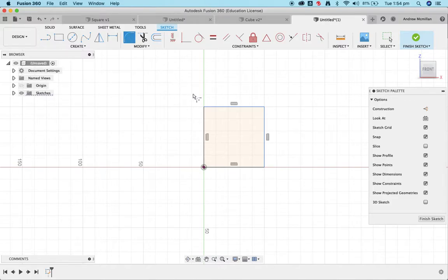Now what you'll find is if you hover over one of the corners on this, a red line comes up which will give you a possible rounded corner. Now I might say I want that to be 5mm. And so it'll just give a really small rounded edge there. I could click on that edge there and this edge here, and that has the same effect, that I can then click on that arrow and just move it in.